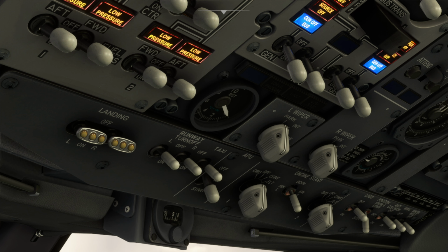Bring it to the on detent here on the start switch, and then we will start the auxiliary power unit. So the auxiliary power unit has now been told to start. We're going to get a caution warning for low oil pressure in a moment. There that is. And we'll see the exhaust gas temperature rise. Once the exhaust gas temperature rises, that tells us that we have shaft RPM on the APU as well as fuel flow and an attempt to ignite that fuel. It'll peak at about 700, 800 degrees C on the EGT, and then it will slowly ramp back down.